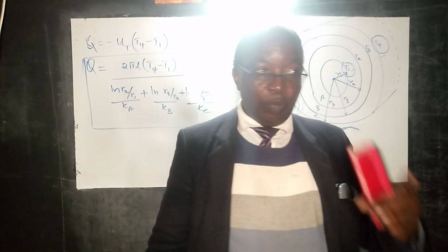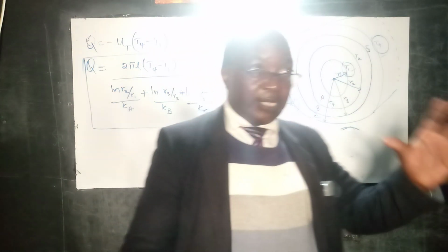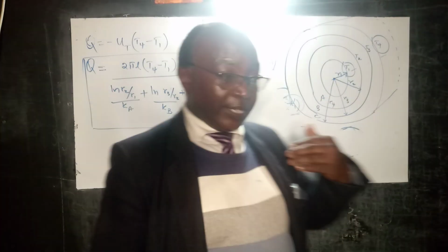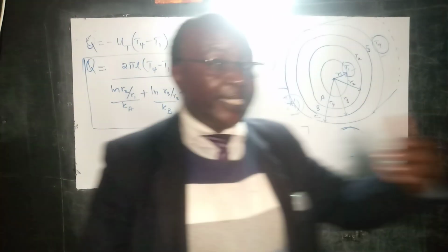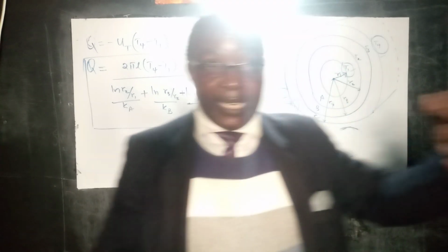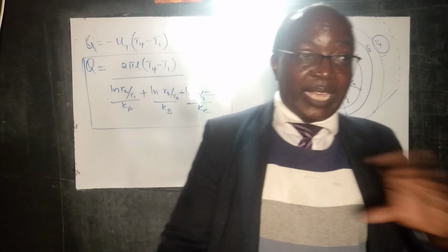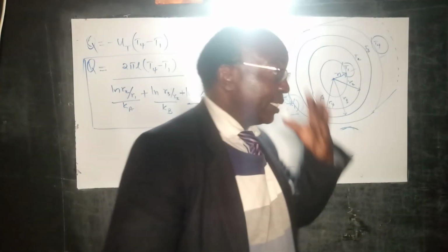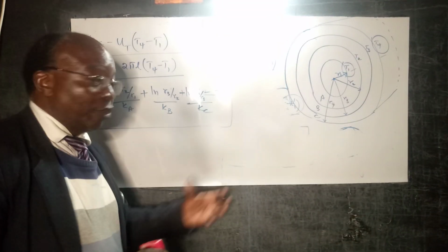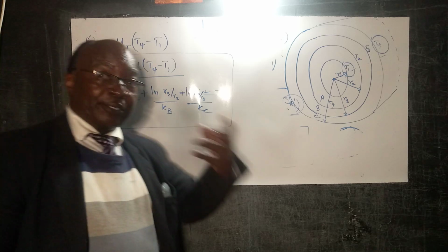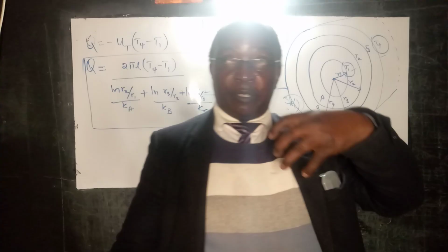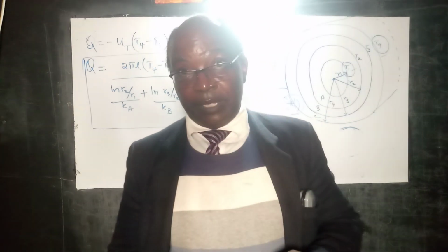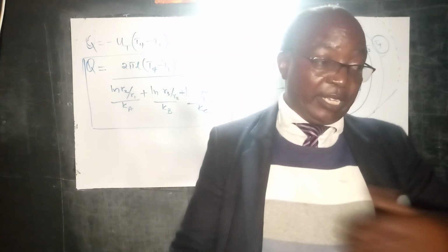And number 2, we have assumed radial steady-state heat transfer. In other words, the rate of heat transfer is basically the same, and those surfaces are isothermal. And so this gives us the expression of heat conduction in a pipe consisting of concentric cylindrical surfaces. The cylindrical surfaces are concentric to the axis.